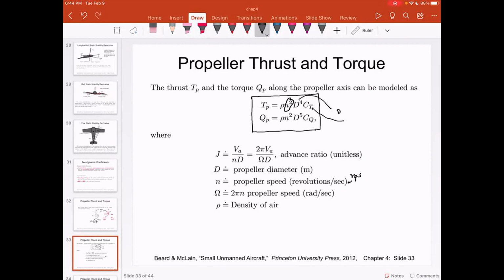If you pull the throttle, then the speed of the prop increases, that increases the thrust, that increases the torque. So the next thing is Cq, which is the coefficient of torque. It also depends upon the air density and the speed, but it depends upon the diameter to the fifth order. Because of the dimensionality, thrust is in Newton, torque is in Newton meter, so you have diameter to the power 5. Now, one thing, the angle of the prop affects the value of Ct and Cq. And please note, in this class, we are talking about props that have fixed geometry.